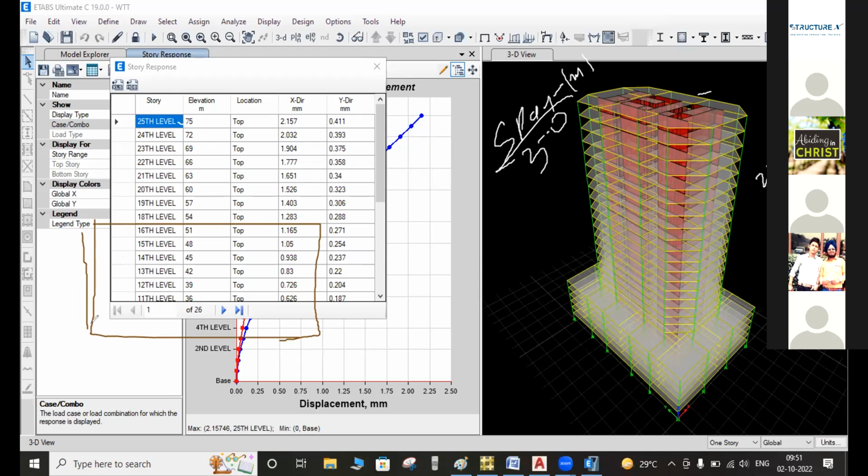So if we have 75 meters here, right, then 75 by 250. This is the maximum allowed value, right, Karim? Sir, 75 is the height. Okay, fine. So you are not saying in terms of height, you are saying in terms of width, the slab span. What spans we have to consider for control here for the 25th story or any story, for allowable displacement?